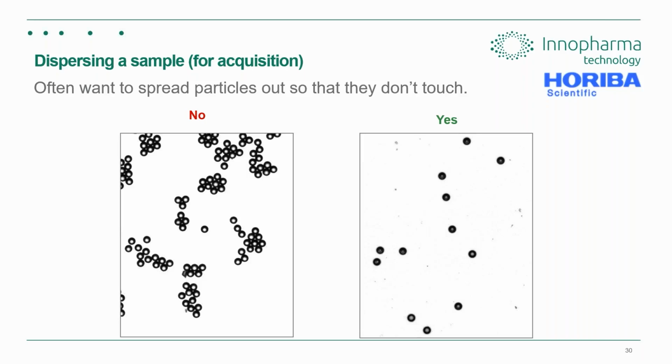Or you could look into mechanically dispersing them. You can use an air jet, or it could be fluidized, or you can use gravity, and the material will naturally fall past the camera system separated. And that just aids your image analysis. It's one less processing step and room for error.